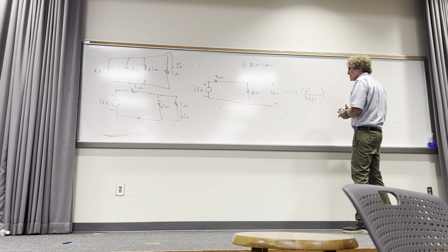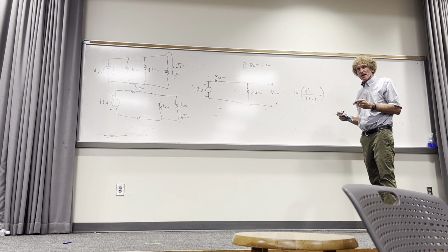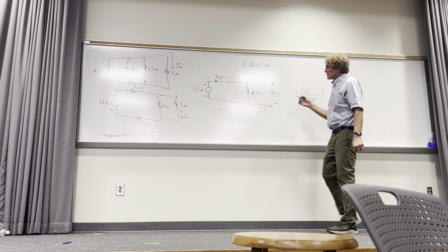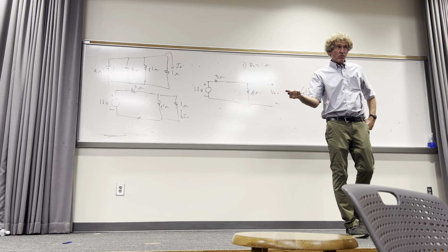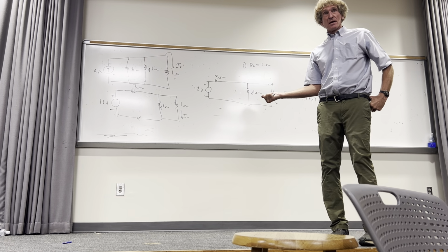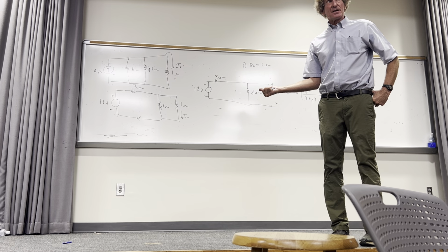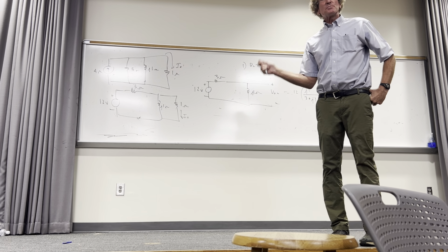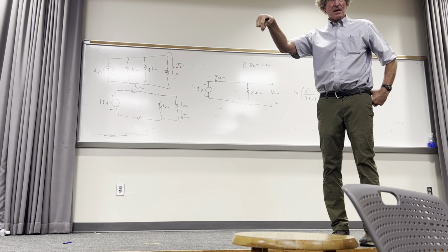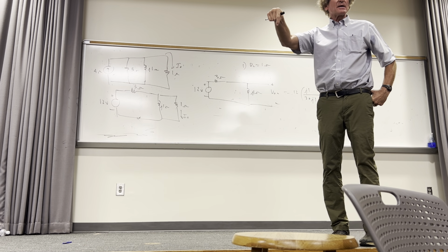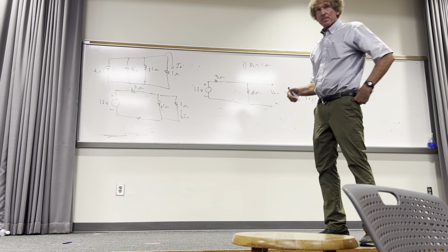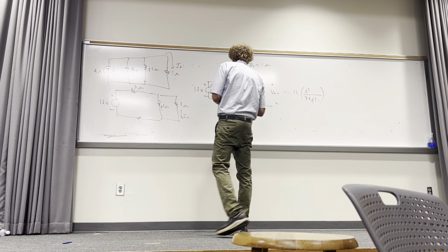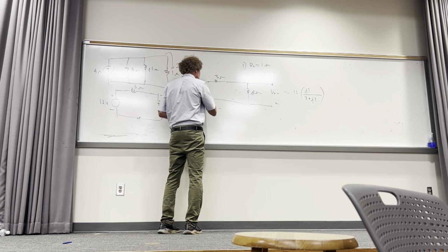So that's the open circuit voltage now, right? What is the next thing we need for the Thevenin equivalent? We got the Thevenin equivalent voltage, right? What do we do next? It used to be called R Thevenin. Or we need to look back and find the impedance across the element we removed. Do y'all remember that class? So if you look back, what happens? Well, this gets shorted, doesn't it?